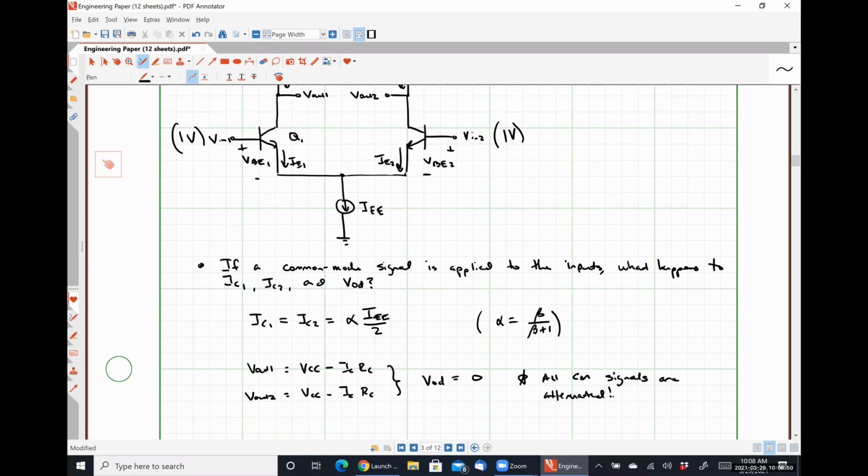This is, I guess, more obvious on an ideal current source than anything else. Okay. So if VBE is increasing, but the collector current has to stay the same, what it's doing is shifting the voltage here at node X up and down to accommodate the changes in VBE, right?